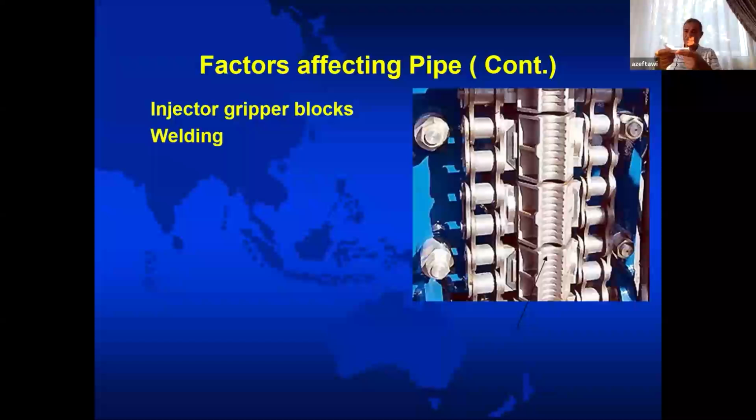And then these strips, we start to make it a pipe where it goes into a series of rollers. First here it bends a little bit, then it bends more, and more, and more, till it becomes a pipe. A pipe, but still we have this end where we have to weld it. This is what we call seam weld. Again, there is no filler material. This is electric resistance weld. There is no filler material as well. We heat these ends together and melt them together.